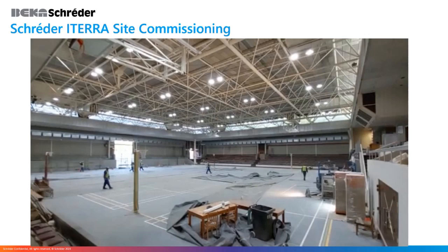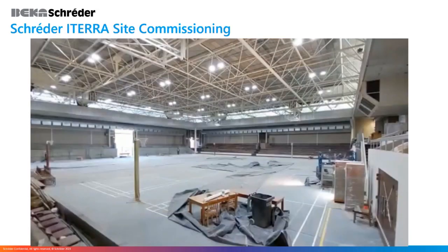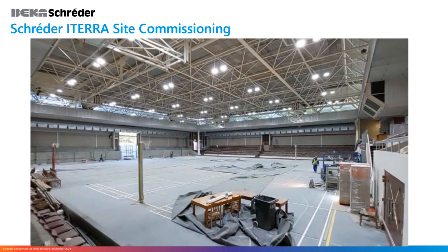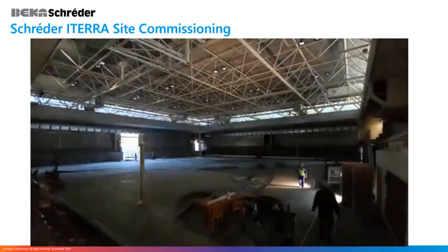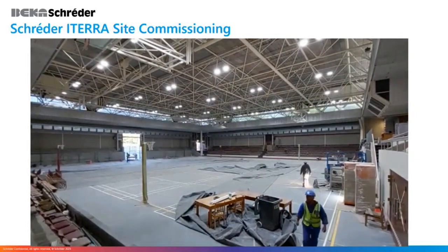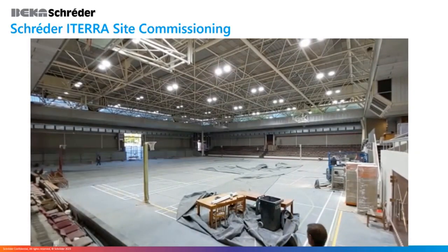Grant, can I also just mention the flexibility? In the beginning you spoke about the protocol and the addressing of luminaires and drivers. What we are focused on here is that with our controller we use broadcasting very easily to address multiple luminaires. However, in this video clip, you can also see how sections of the lights are switched on and off. Those are sections of luminaire drivers connected to one node, where I'm broadcasting to a very specific grouping of luminaires. There are limitations to how many addresses we can do per node, and this is 8.